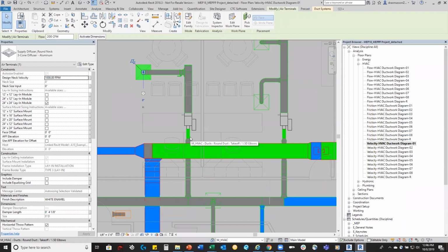And I know that is 180 degrees out of phase of how we have all thought about flow in ductwork throughout our entire careers, right? This is not how you're taught to size ductwork in school. This is not how we think about flow. We always think about it coming from the piece of equipment. That being said, this is how Revit works.